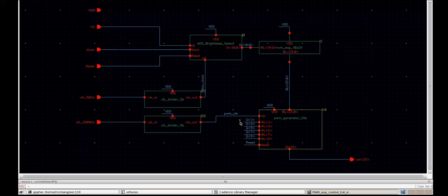The output shift register needs to run at a higher frequency so that you can see the lights with no flickering. So in order to get a 120 Hz signal out here, we need a 3 kilohertz signal here, which is divided from a 200 kilohertz signal from the PLC.